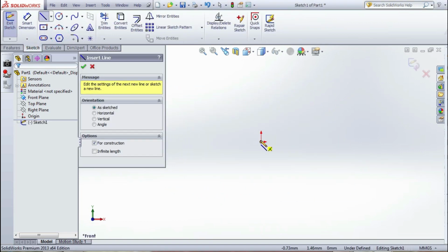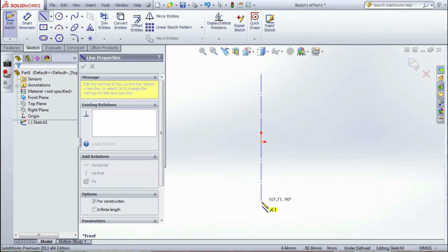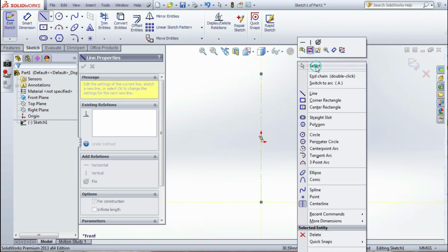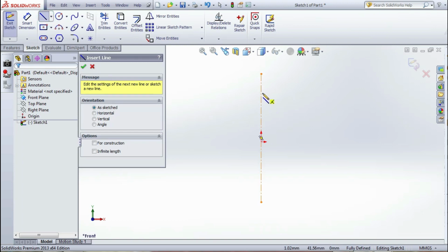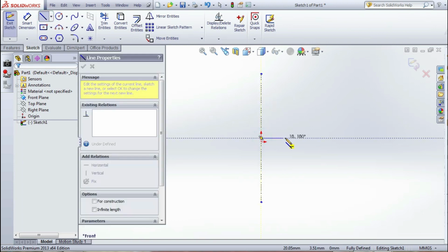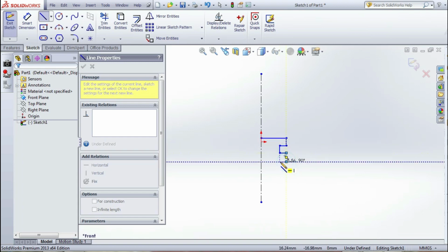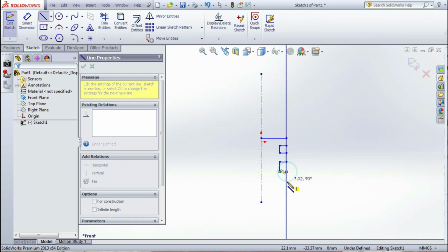The same thing, sketch and front plane. The front plane is the same plane; using the same plane makes the final assembly very easy. That is what we use many times, the front plane for the frame. Now we're going to draw the piston. This piston uses the revolve command. We can use the revolve command to make a piston.